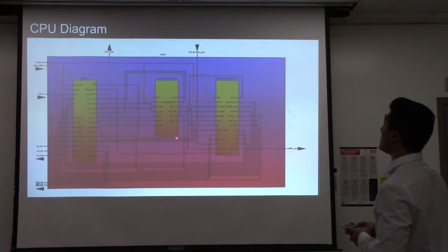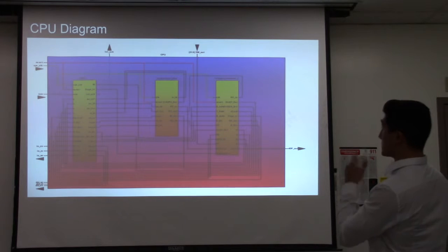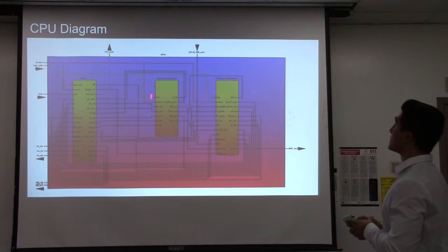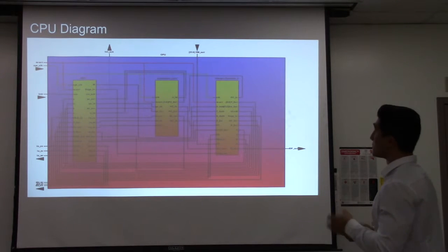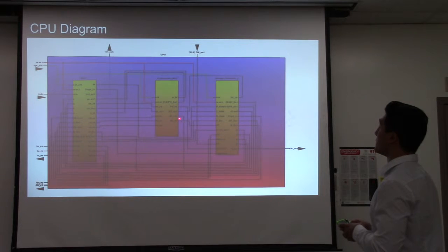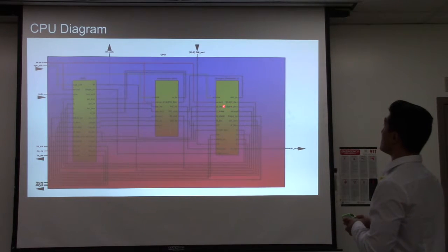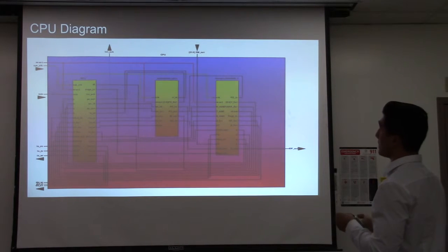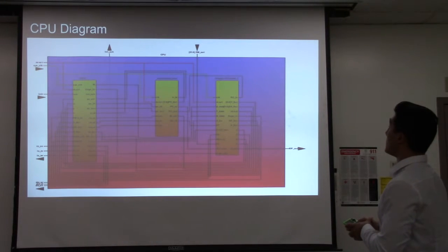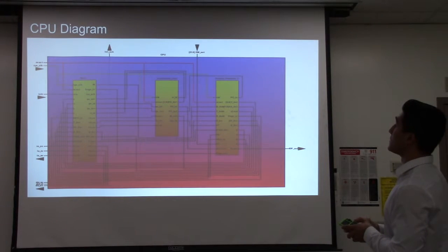First, I'd like to start out with the instruction unit. This is basically where we're getting all our 32-bit instructions from. It has a PC register, an instruction register, and our instruction memory. Let's say we would like to pull out an instruction from here. It gets pulled out from IR out. It's a 32-bit signal. And some of it gets sent into the integer data path in order to get the S addresses and T addresses, or D address, based on the subset of the instruction word. And the opcode of the IR out gets sent into the MCU, the MIPS control unit.